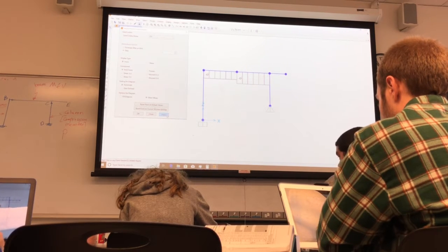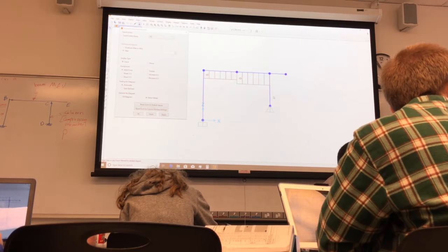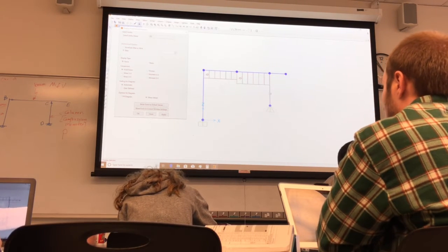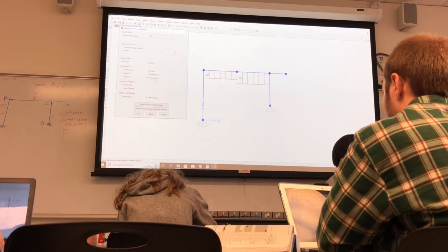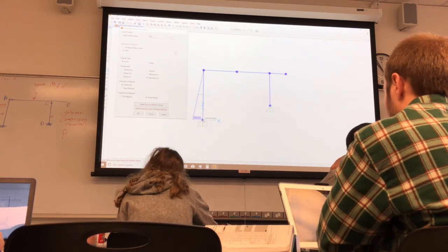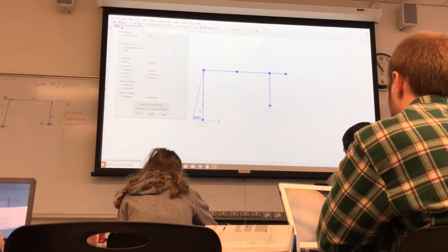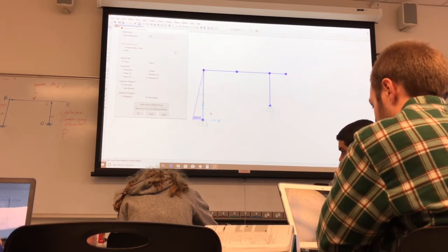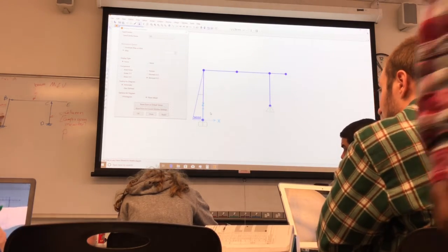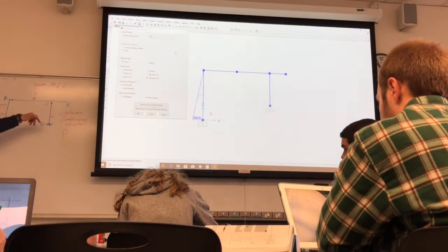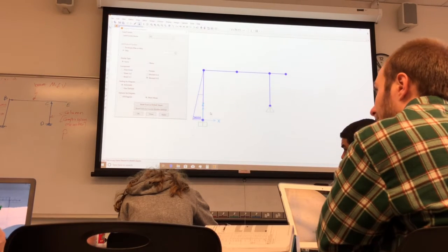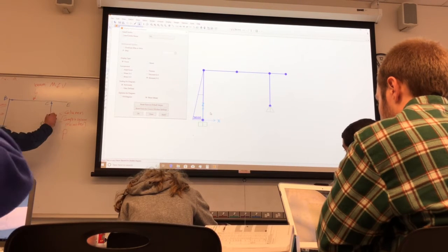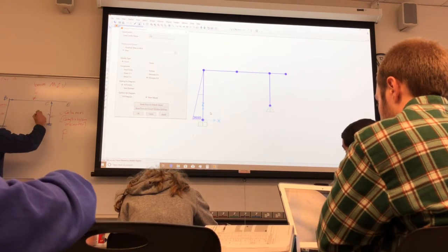You do get shear and moment in the columns when you have the lateral loads, though, right? Not this one, but the other one, because that one is fixed. We call this one a beam column, because it's a fixed support. That's why we're getting all the shear and moment in this one, but we're dealing with the CD, pin top and bottom. So we call this one the leaning column, you know, in design.